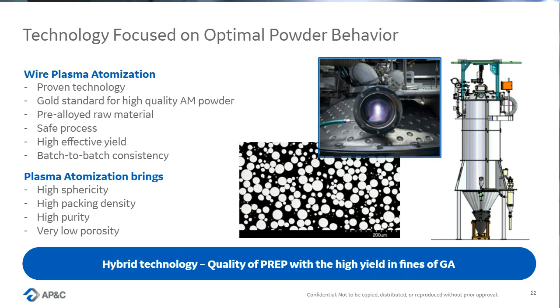Simply because by doing that, we can always have the right energy to mass balance to have the right powder. And also with wire atomization, we never need to empty the crucible or finish the rod. The operator can stop the process at any point in time and ensure that we have a consistent product and always select product quality over performance of the equipment.